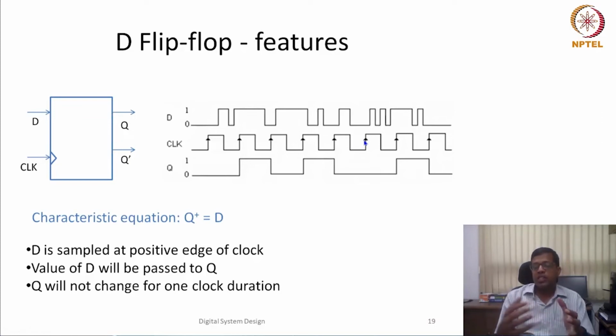So this gives us an additional constraint on our circuit: if my circuit has a certain delay, I can set my clock period accordingly. Or in other words, if my clock period is fixed, then I can make my circuit such that it stabilizes its output before the change of the clock period.